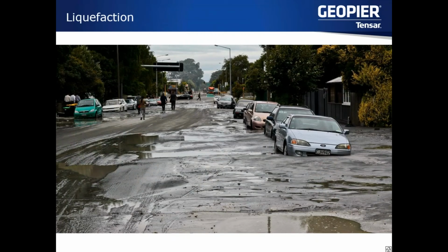And thankfully, something like a magnitude 5 isn't nearly enough to cause liquefaction. Without going into all the specifics of effective stress, the mechanics involved, essentially with liquefaction the ground shaking is so severe, it reduces the shear strength of saturated granular deposits to basically nothing. And that causes these saturated deposits to flow as if they're a liquid without any shear resistance. And that's what we see here.